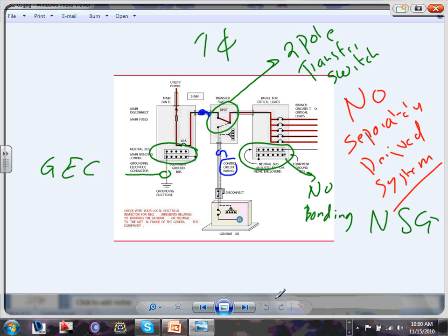Okay. I will bring to your attention, guys, if it's a generator, you need a disconnect for the generator within sight of the building. You guys remember there's an exception that they created in 2011 that if this building is under certain management and only qualified people handle it, you don't have to have this disconnect within sight of the building. But the best thing is to have it. So we have a disconnect over here for the generator. Remember, you have to have a disconnect for the generator.